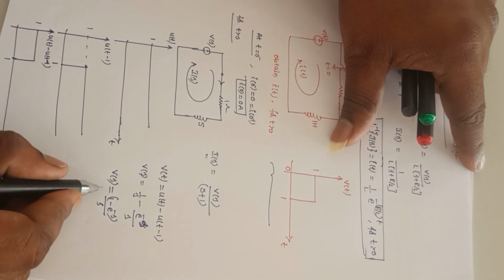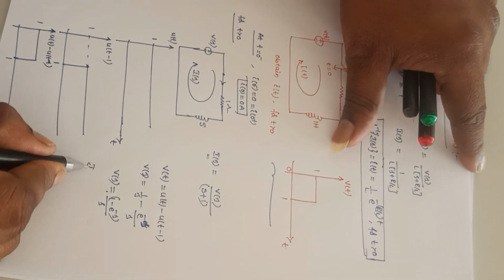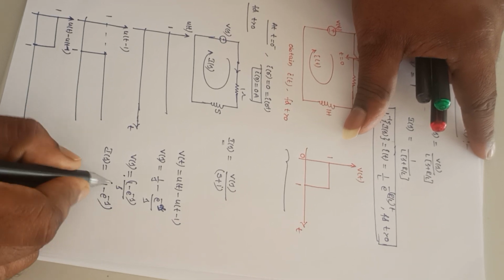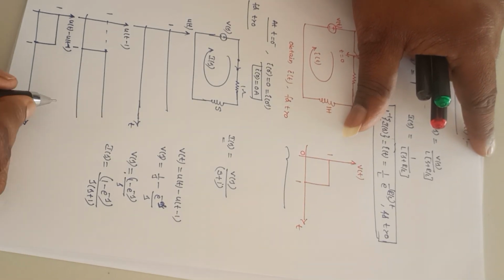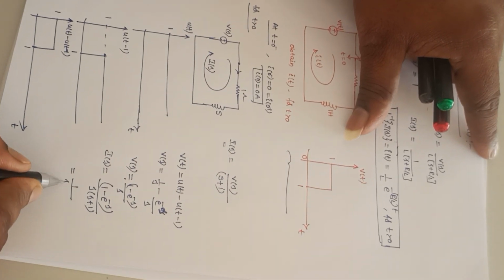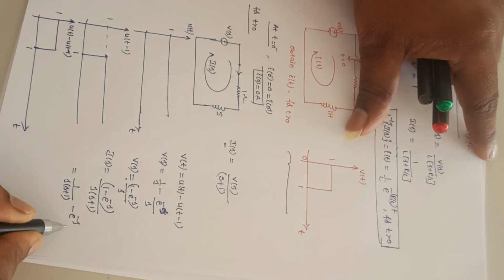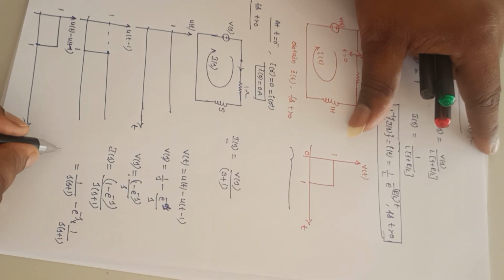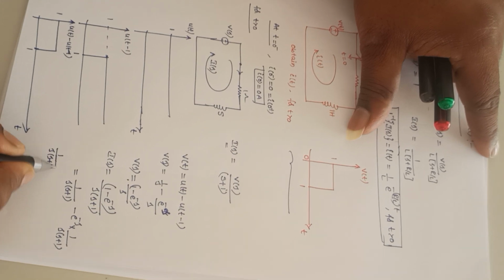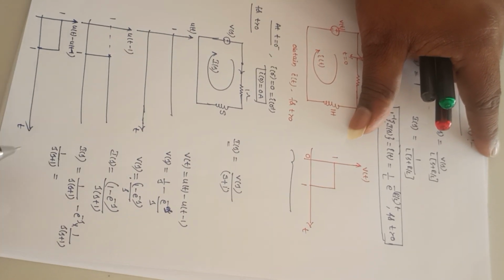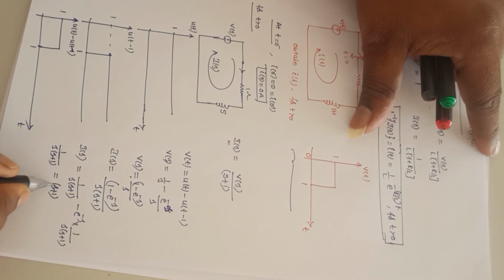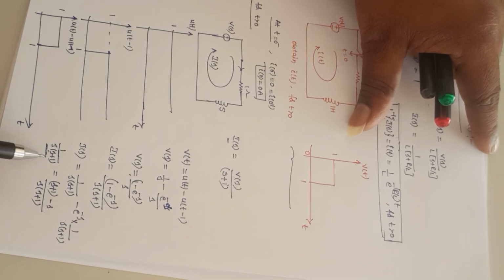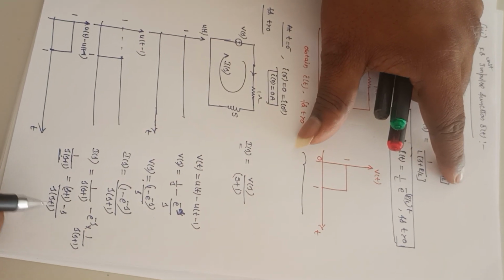If I substitute this in this expression, I(s) is equal to V(s), which is (1 minus e power minus s) divided by s, into 1 over s plus 1. So it is 1 divided by s(s plus 1) minus e power minus s into 1 divided by s(s plus 1). Now this 1 by s(s plus 1) I can write as (s plus 1 minus s) divided by s(s plus 1).